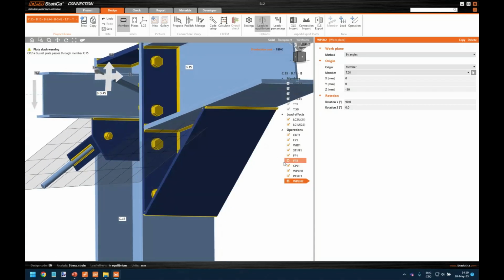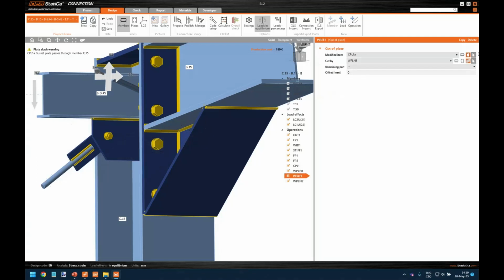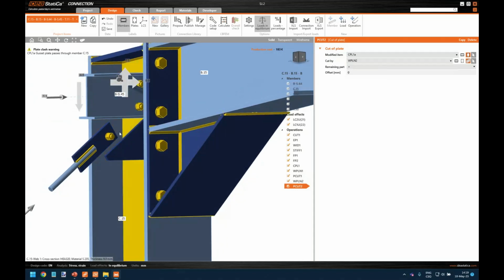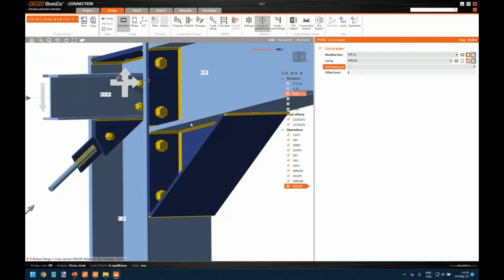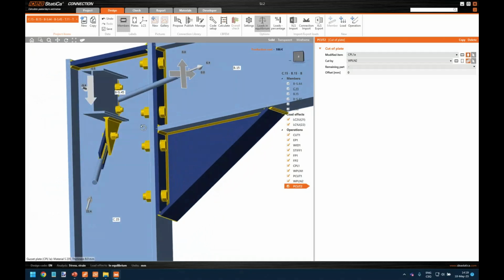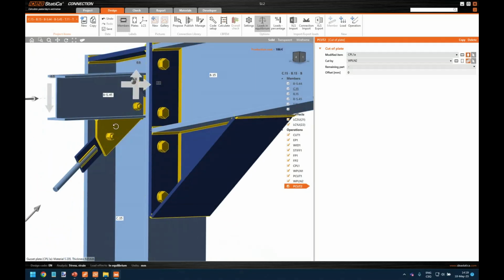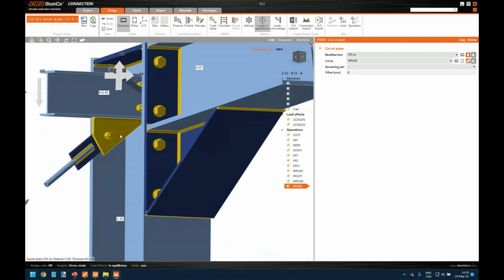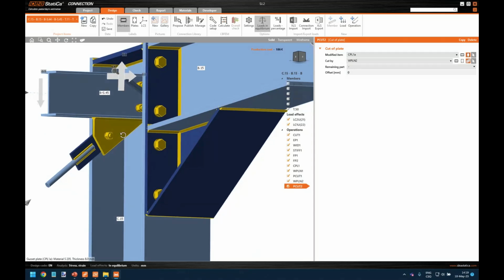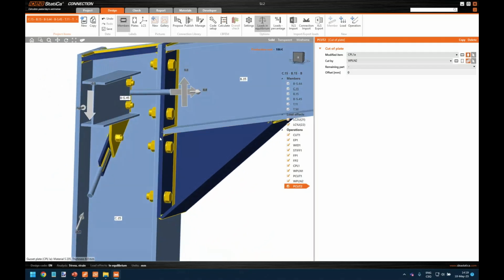And you can see probably already my goal that I will use another P-cut operation and just choose the different plane and revert this cut to cut this off and leave this here in the model. And this way I have shaped this gusset plate of this connecting plate operation. Good, that's for the one.